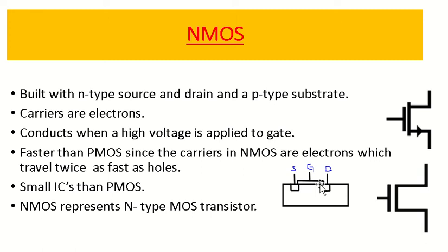Coming to the symbols, we will quickly understand them. This is the symbol of NMOS, or we also mention it in this way in the case of CMOS. While drawing, we usually use this symbol as well. You have to be familiar with both symbols: this is NMOS, and this is also NMOS. These two kinds of symbols can be used for NMOS type of logic. We can say NMOS is a logic, and PMOS is also a logic. Both logics taken together build up CMOS logic.